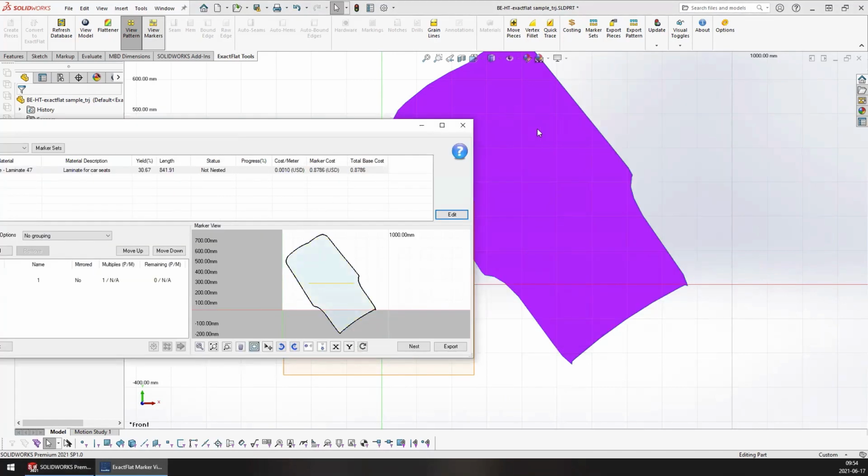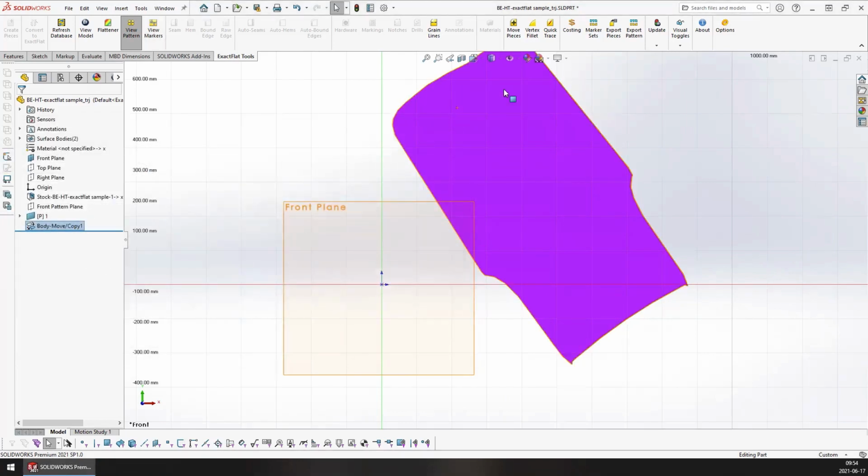So with this mode, you can rotate your pattern pieces and line them up so the grain line is always going to be projected on as the x-axis. It makes it a little bit easier to control the orientation of your grain line. Ultimately, though, the most control is given by the grain line tool here. However, we do strongly recommend that if you're going to use this tool, it has to be the very last operation that you apply. Otherwise, it will introduce instabilities into the workflow.